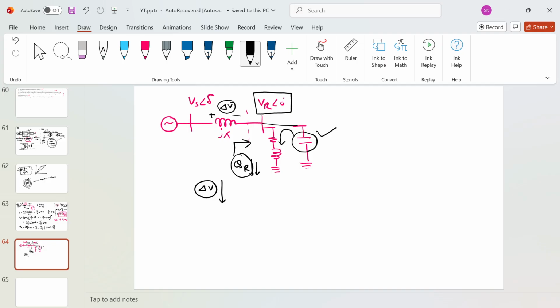This is about the shunt compensating device. We also have series compensating devices, which I will discuss in the next questions. But I hope it is clear. If you have this compensating device, you will have less drop, and by having the reactive power compensating device, you can get good voltage. You can say good power factor. The power factor that you will get at the receiving end will be very good.